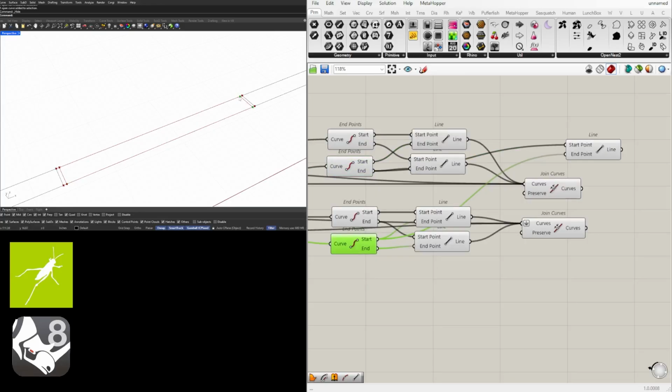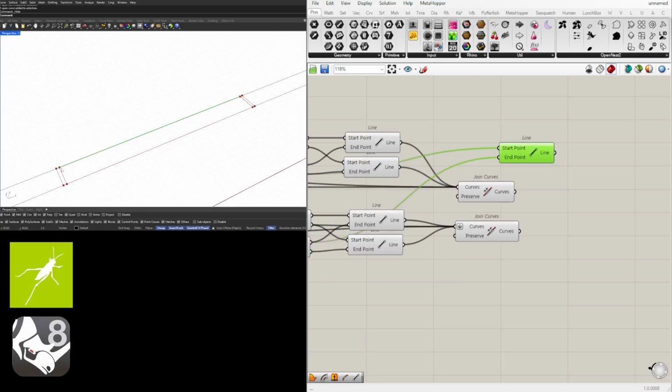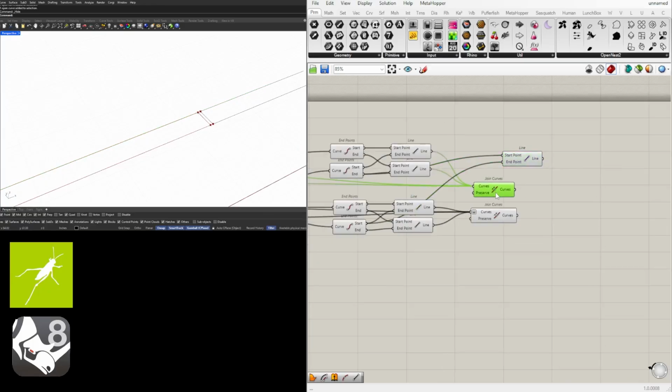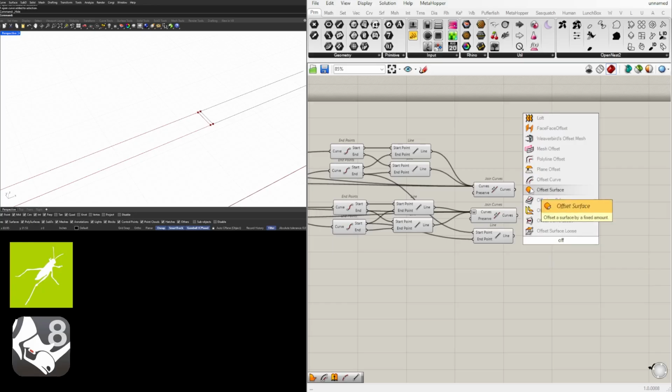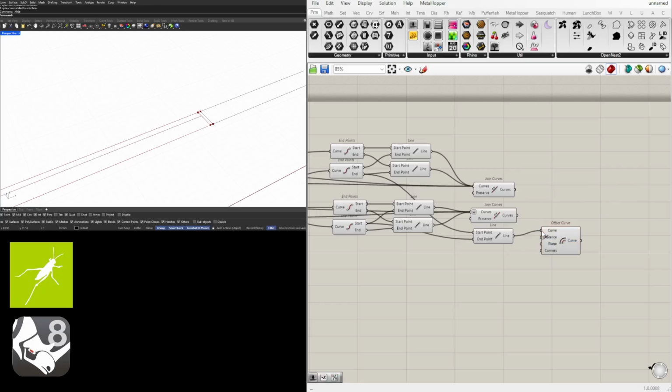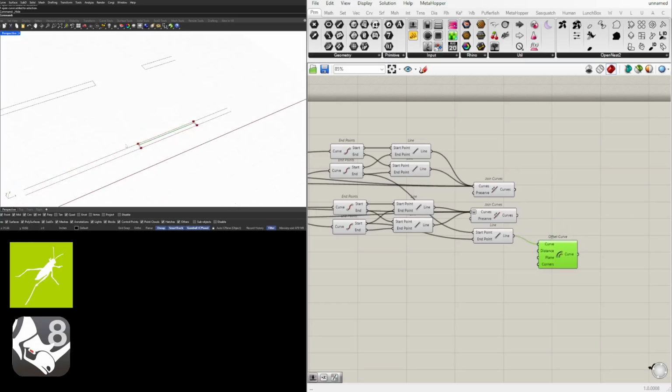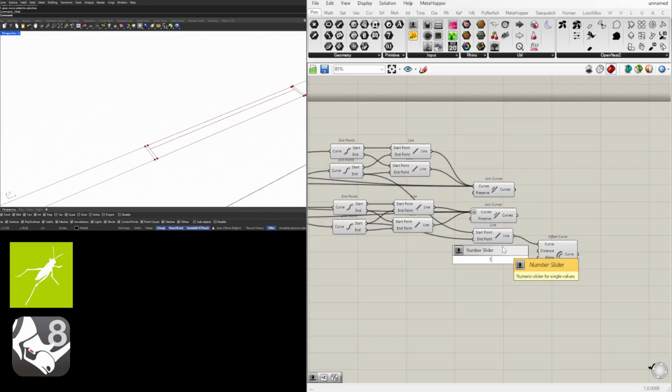And the reason why is because the way that this was organized for you to offset it to the inside, it's going to have this be organized different than this one. So you just have to make sure that you have the line segment starting on the inside of the frame and ending on the inside of this side of the frame. Now we're going to offset this to create the door depth. And depending on the door size, for me, it's going to be 1.75.